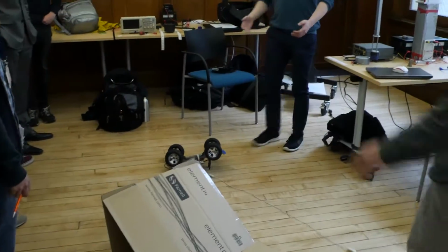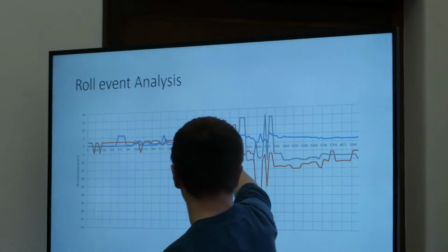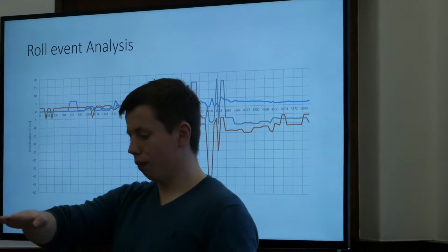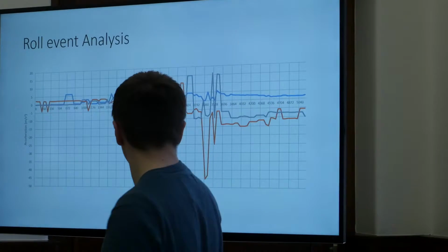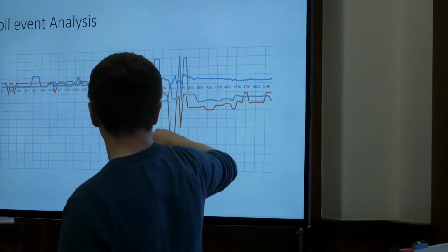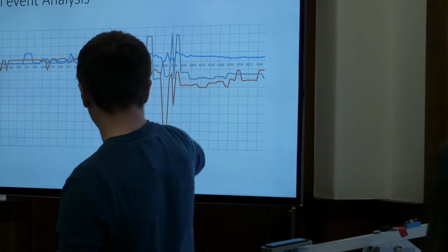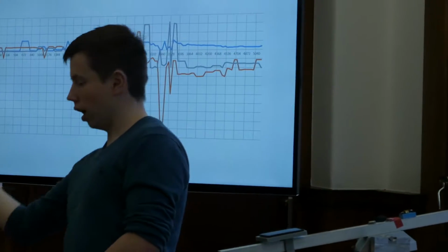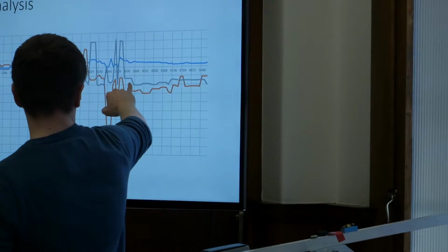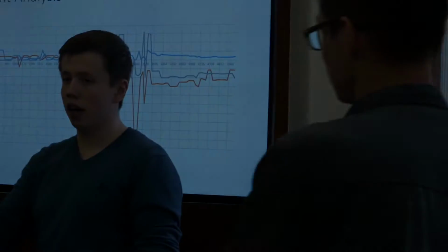This is the most complex event to analyse because this is hitting the ramp itself and this is coming off the side. Obviously, it came off sideways and then fell onto its side first, hence the big change in Y, and obviously in Z as well. So it's upside down. You can tell from this trace that it fell to the right and then landed upside down, and then it settles. But the accelerometer settles at a different height because of the angle it's sitting at.